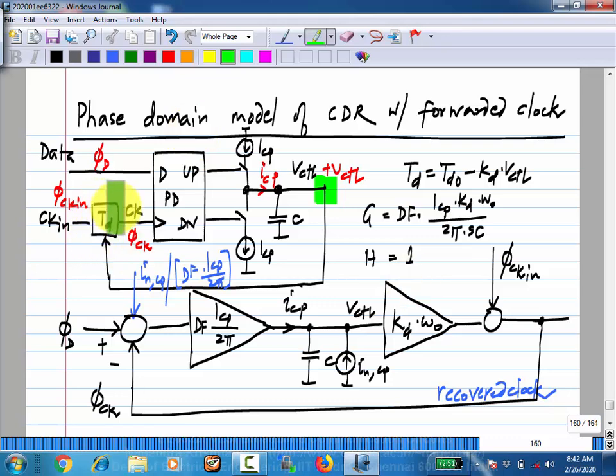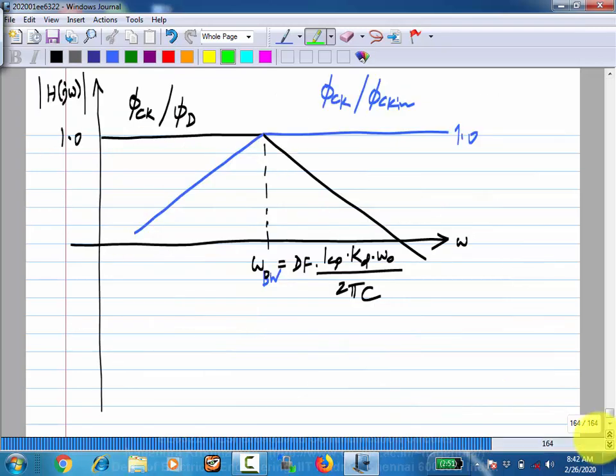The delay itself will have noise. How do you make a delay? You make a delay using, let's say, some inverters, and then you have some input. When the input crosses some threshold, the output starts rising, and then you will have a delay. Now there will be some input referred noise. So the instant at which it crosses the threshold is also influenced by the input referred noise. So the noise of these stages will cause jitter, right? That is, even if the input doesn't have any jitter, the output will have jitter.